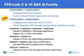If you go back further, there was the DS90UR 241 and 124 that's used in many systems, and that's 18-bit with strong, good EMI performance there as well. There was a set of products, the DS99R 421 and 124, that do conversions to support native FPD-Link III devices. So devices that either generate the FPD-Link III signal or receive it. And then the DS90C 241 and 124, which are in many camera applications today.